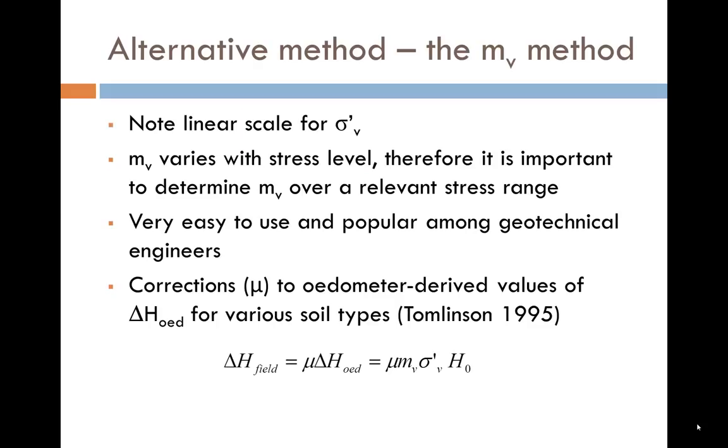A few points about the mv method. First of all, note the linear scale for the vertical effective stress. mv depends strongly on stress level. Therefore, it's important to determine mv over a stress range relevant to the problem being considered.